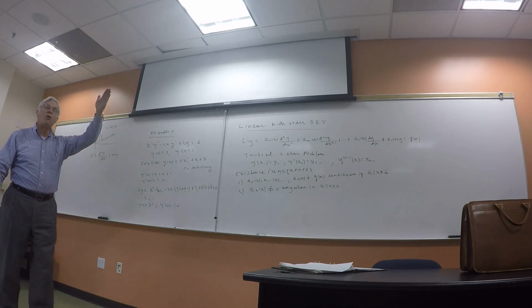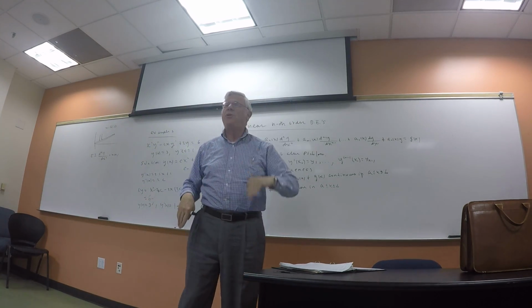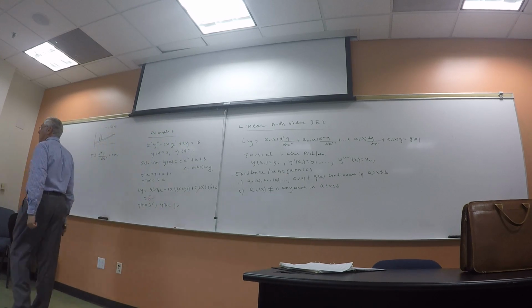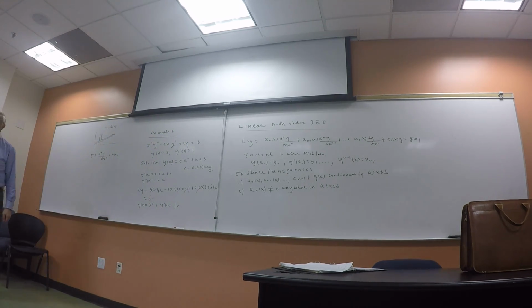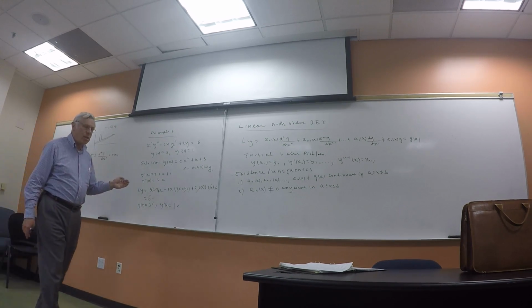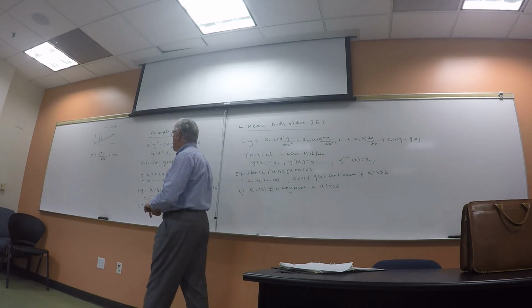Maybe it's like in your car when you have an antenna and then there's a wind load. It bends when that happens. Or it could be a building even. The buildings aren't modeled by Euler-Bernoulli beams, so a car antenna is probably a better example. So this is the equation, called Euler's equation for the bending of a beam. It's actually an approximation. It's linearized. It becomes much more complicated with the nonlinear model.